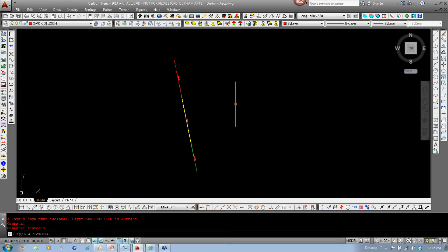And then we have another question: can trench width be based on pipe size? You can basically, and I think Todd will probably get to some of this in just a minute. You can. I basically created my trench to add 18 inches on each side of the pipe. So as the pipe size increases, that trench width increases 18 inches on both sides. Okay, that's all the questions.